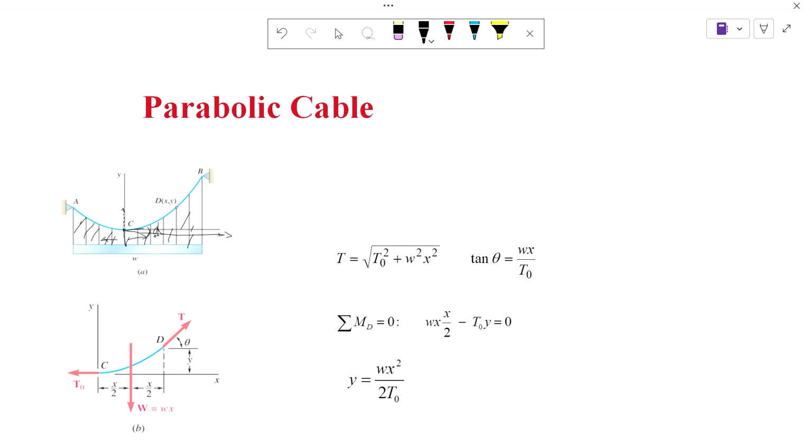So when you place your W, you follow the table that we've seen before. If it's a parabola, it could be at x over 2. If it's a triangular shape, if this is completely in tension, then it's probably going to be a triangle, where you find the W and place it at 1/3 or 2/3 of the base, depending on where you are. Okay, so in this case, it's the same. The only change that we have is how you compute W, which is the most difficult part.